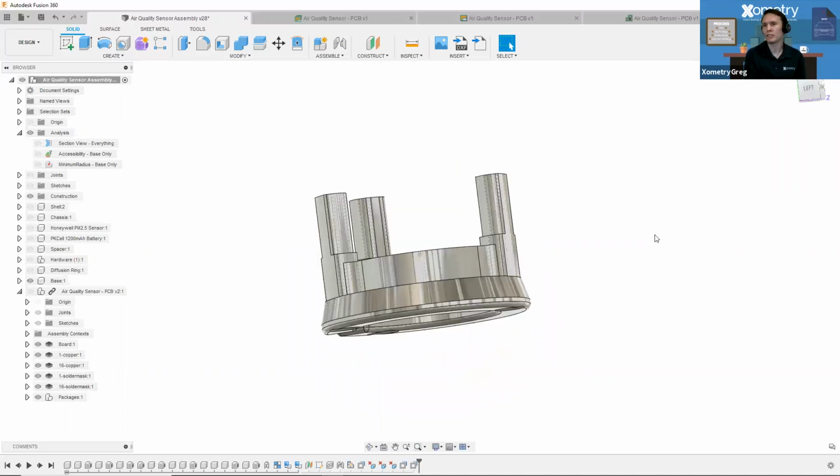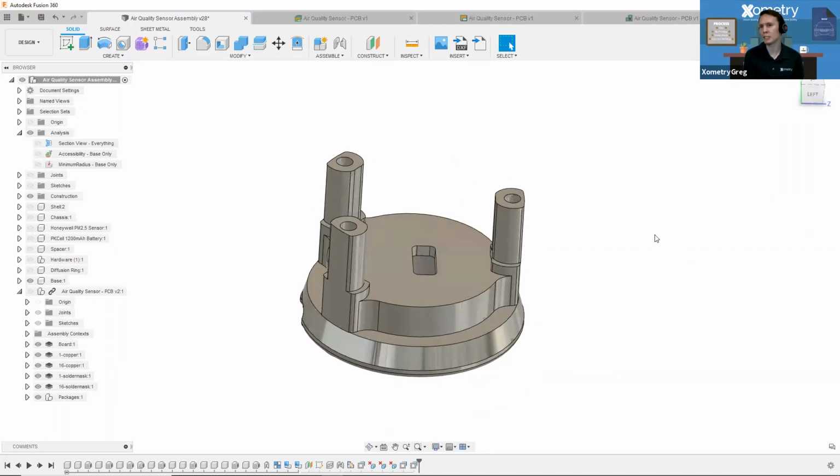So we were talking about this a little bit earlier, like what would it take to make this part? This would probably be made on a 3-axis mill with two setups. So doing one side, flipping, using soft jaws to hold it, and then doing the secondary operations of this part. So overall, the cost of this is now just those two operations and removing the material around this boss feature. So I think you're pretty solid.